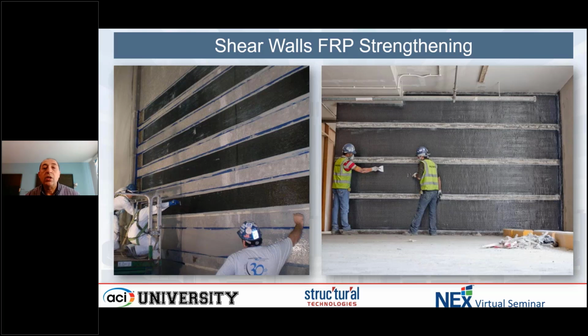I think one thing I should mention, just to make sure there's no confusion, since there was a question to Kent earlier, is when we deal with seismic, there is typically no upper limit for the FRP. So there is no requirement that the structure can take 75% without the FRP, because seismic is an extreme event. It's one in a lifetime that may or may not happen to the structure. And when that happens, we're trying to get as much capacity as possible to prevent failure of the structure, improve the life safety and safety of the structure in general. So the code allows us to fully utilize the capacity of the FRP, because again, it's an extreme event, less likely to happen.